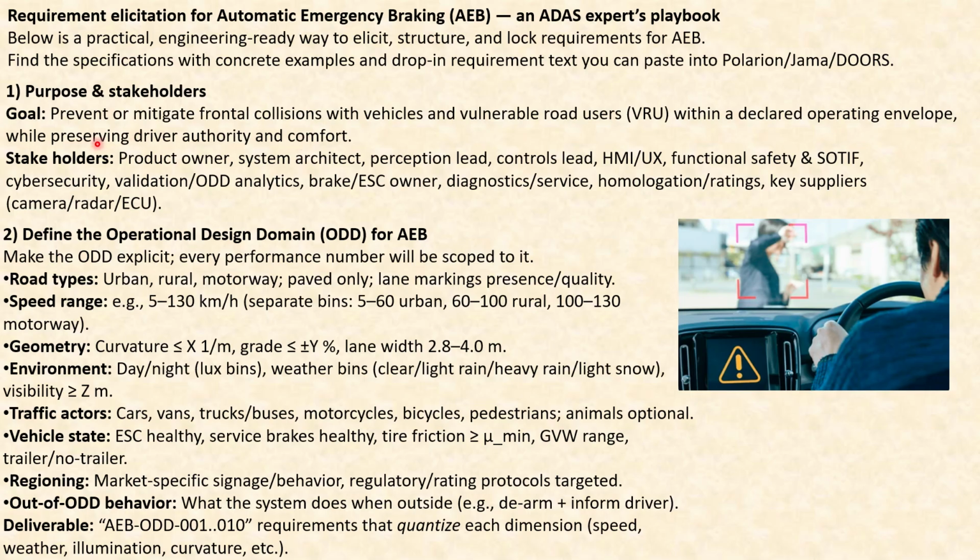All right. Now, when it comes to stakeholders, who are the stakeholders? Product owner, system architect, perception lead, controls lead, human machine interface, user experience, functional safety, and SOTIF, which is the acronym for safety of the intended functionality, cybersecurity, validation, operational design domain, brake and electronic stability owner, diagnostics and service technicians, homologation and ratings, and the key suppliers like camera, radar, ECU. So these are all the stakeholders in this requirement elicitation.